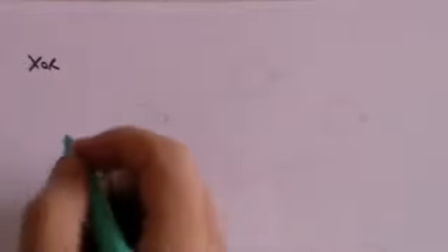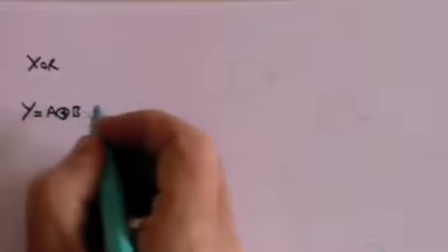The next one we're going to do is the XOR gate, and let's move that over so you can see it, and that has representation of Y equals, Y is the output, don't forget, A plus in a little circle B. And that means that either one of the inputs is positive but the other isn't. So one can be positive but not both. And here we actually have to use other gates. They will contain transistors, but we need to use actually 4 NAND gates to create an XOR gate. And that's how you start to see how these gates build up in logic terms.